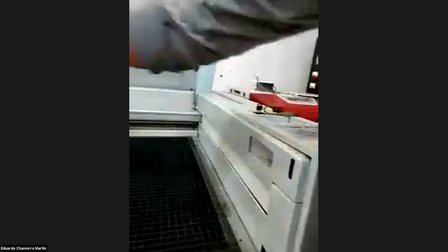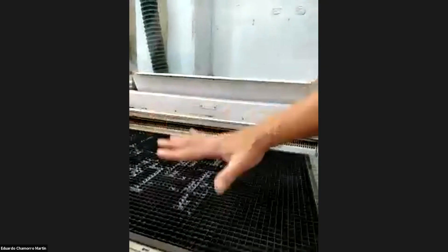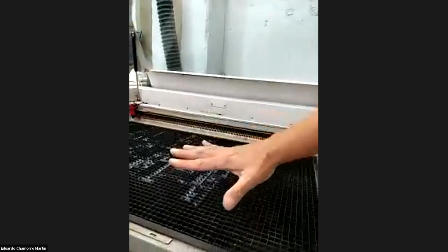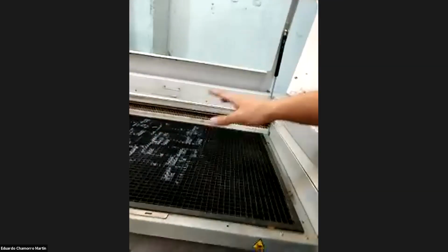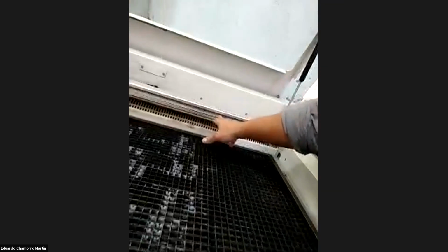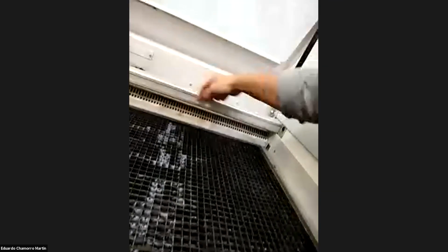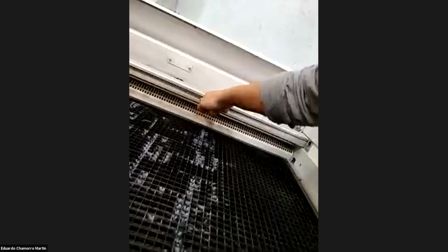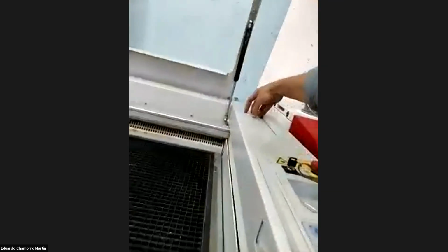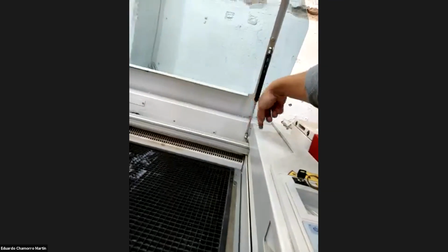Here, for example, the Z moves with a ball screw, because we have 1, 2, 3, and 4 ball screws to move all the platform down eventually, with small and really controlled movements. Meanwhile, the X and Y need to be really fast. So actually the belt is hidden in the profile. This is a Y profile that is coming here and coming in the back. And we have the motor held exactly in the same profile with teeth.